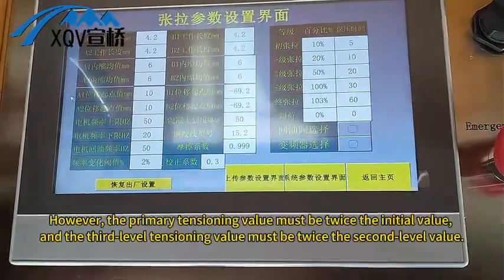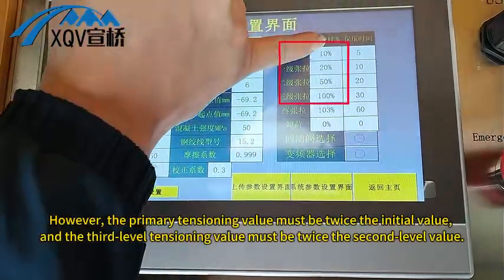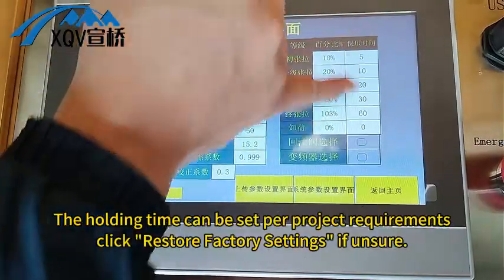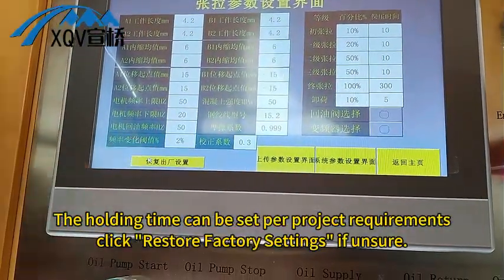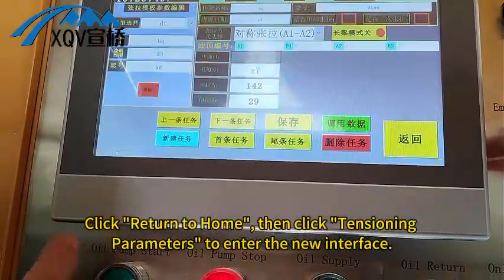However, the primary tensioning value must be twice the initial value, and the third level tensioning value must be twice the second level value. The holding time can be set per project requirements. Click Restore Factory Settings if unsure. Click Return to Home, then click Tensioning Parameters to enter the new interface.